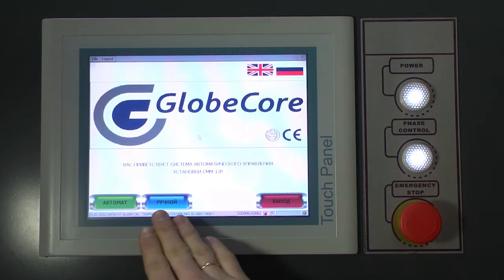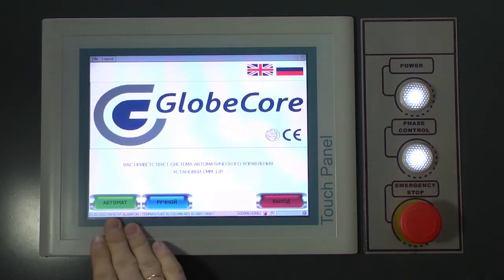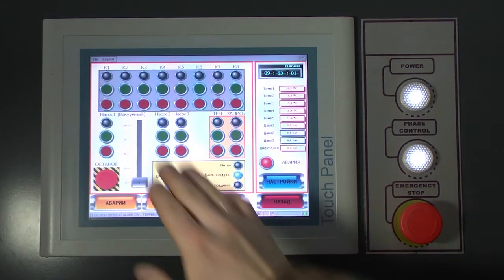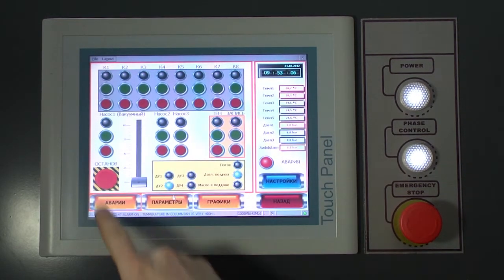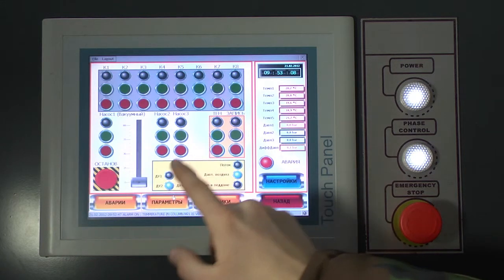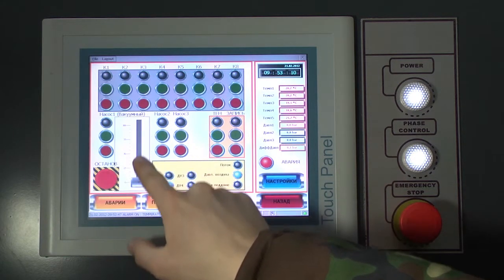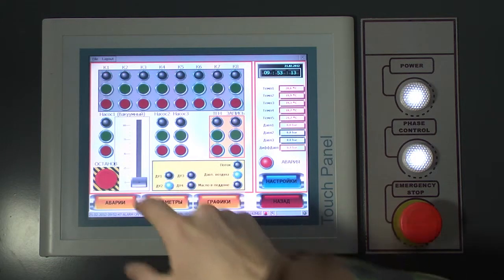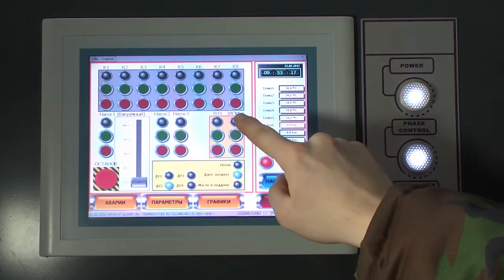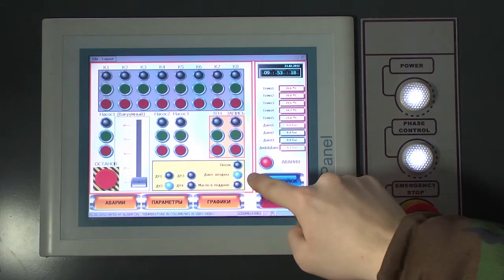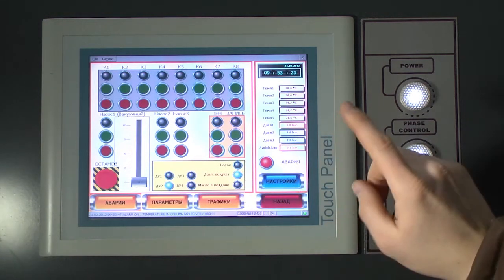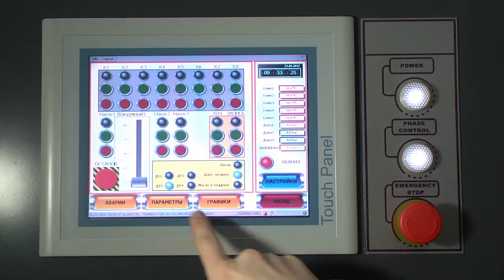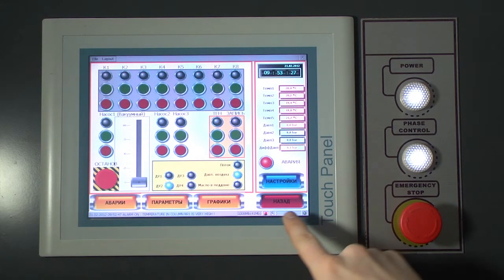It features manual and automatic operation modes. The manual mode makes all valves, pumps, and the vacuum pump accessible for direct control. Pump rotation speed is controlled with a slider. The panel displays oil flow, air pressure, presence of oil in the base, emergency shutoff, graphs, parameters, and malfunctions.